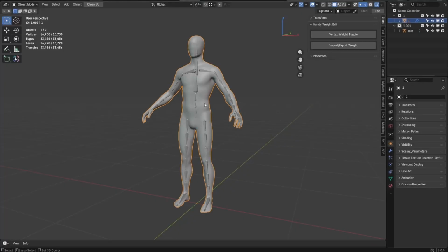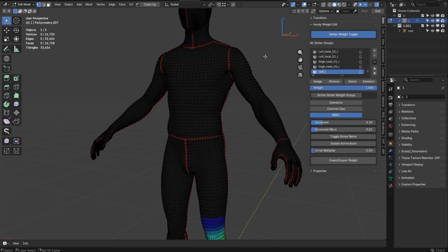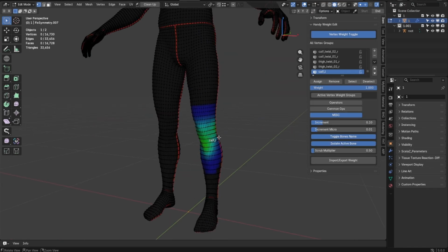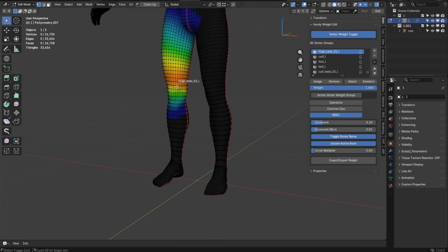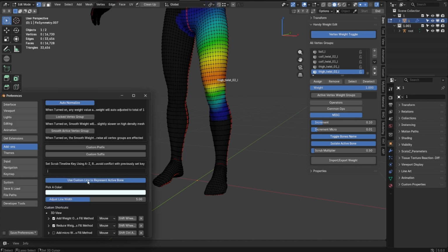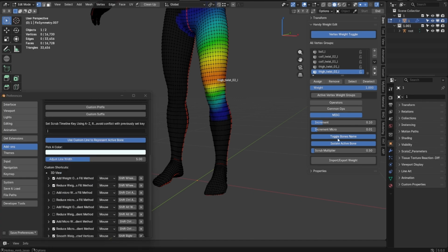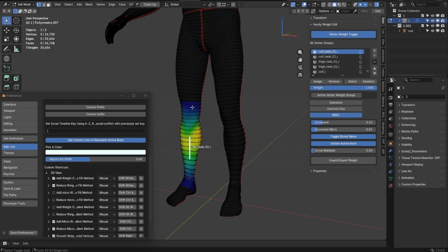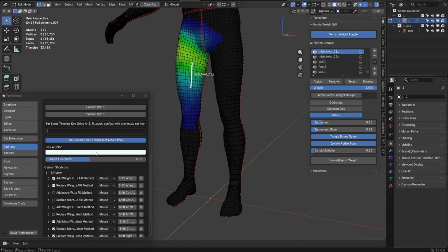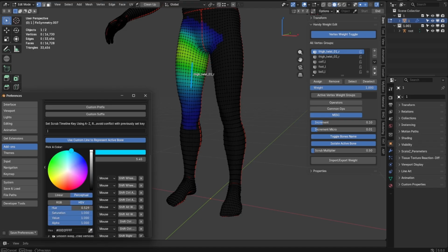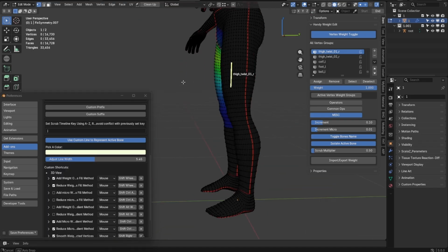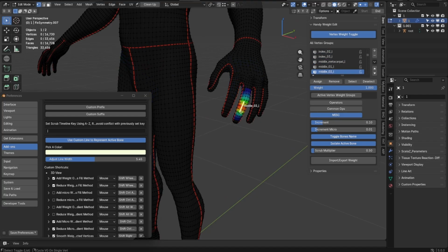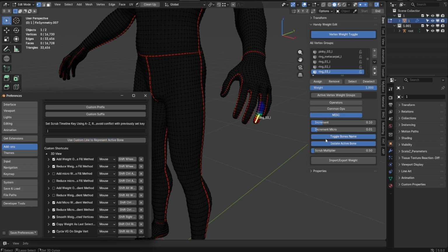If the bone In Front effect does not display properly, you can turn on the custom bone highlight. Go to Add-on Preferences and turn it on. At the active bone location, a new highlighted stick is drawn. This better represents which and where the active bone is. You can adjust the color and width of it. When the Isolate Active Bone toggle is on, or when you use the Switch Bone operator, it is automatically adjusted.